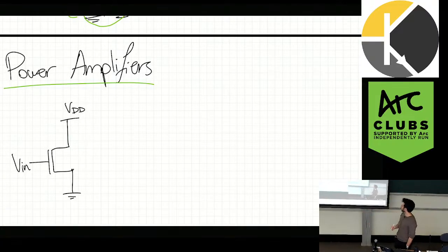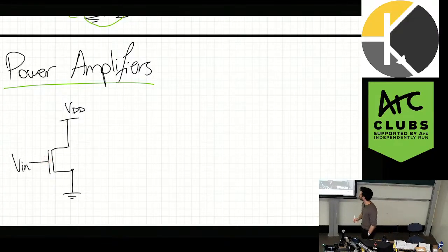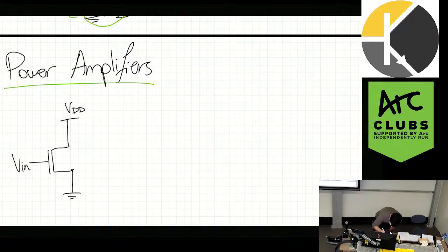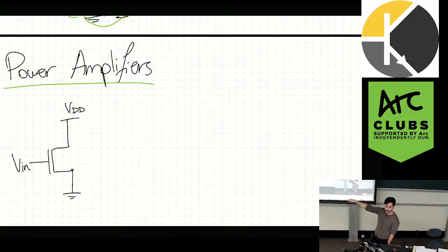Now, what are the two conditions to turn on a transistor? NMOS. So a PMOS would have a little bubble here, like that. What's the condition to turn this on? So the first condition is that we have to apply a positive enough gate voltage to turn this on, right? Because remember, the channel in NMOS is full of negative charges, right? N-doped MOSFET. So that means we have to apply a very positive charge at the input to attract those electrons up and form a channel from here to here, right?